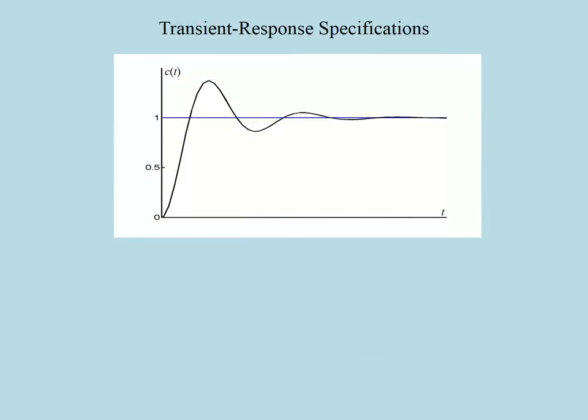From this discussion, we understand that the output of a second-order system is shaped by the parameters zeta and omega n. On the other hand, in synthesizing such second-order transfer functions, we need to also understand the relation between these parameters and the time domain specifications that are given to describe the behavior of the output. Therefore, we shall continue by defining some typical transient response specifications which are used to define a desired behavior of the output for a step input.